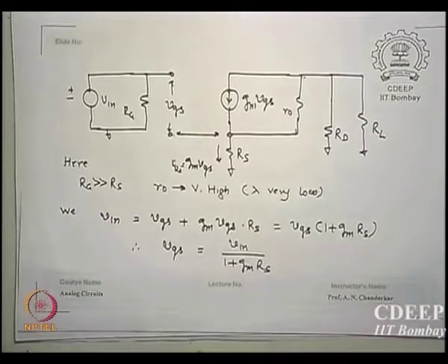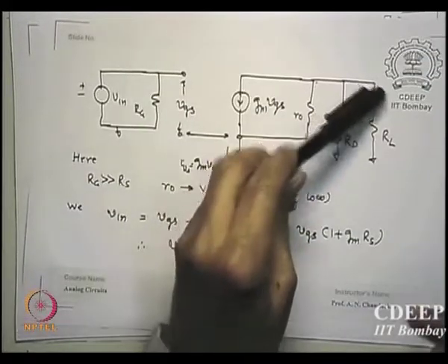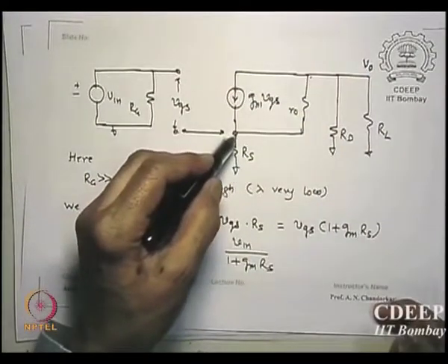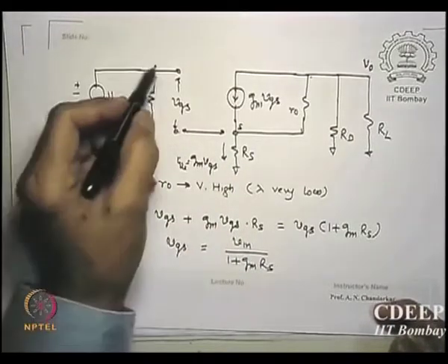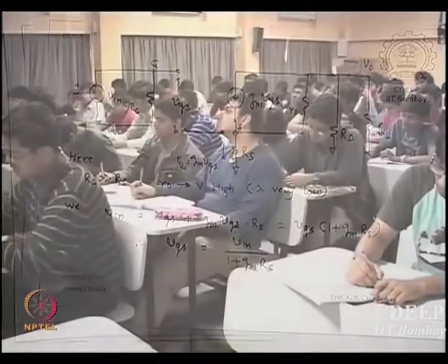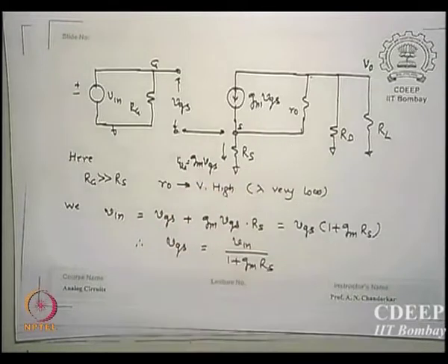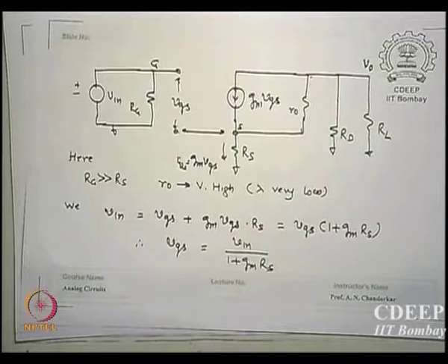So, equivalent: have you seen this? Please look at this circuit. This RD is grounded, this RL is grounded, this is of course your V0, and this is your source, which is not grounded. So I should not connect RD parallel R0 parallel RL now. Is that point clear? The difference is that RD and RL are parallel but not parallel to R0, because they are two grounded. R0 is only going to the source, because that is how I define R0.